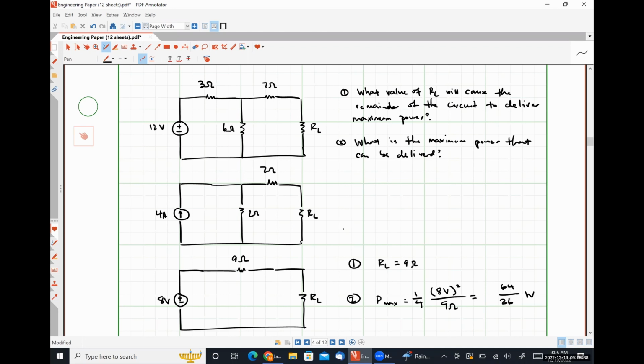And then from there, our power calculation is pretty straightforward. Imagine trying to figure out what value of RL would cause maximum power transfer without using that simple representation. It would be nearly impossible. It would take hours of trial and error. Whereas with a practical voltage source or current source representation, power relationships are rather trivial, okay?